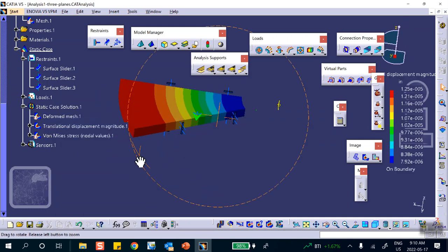There. Okay. We solved the problem two ways. As in the book, did not use half plane of symmetry. That's why I had to say select one point and say it can't go up and down. Then I did it like that, halfway through, okay? And I don't need that restraint. That restraint would not have mattered anyway because you kept the bottom. It's going to complain to you that it's not there. You put it at a point that's gone already. It's okay, you would have run, but any questions?